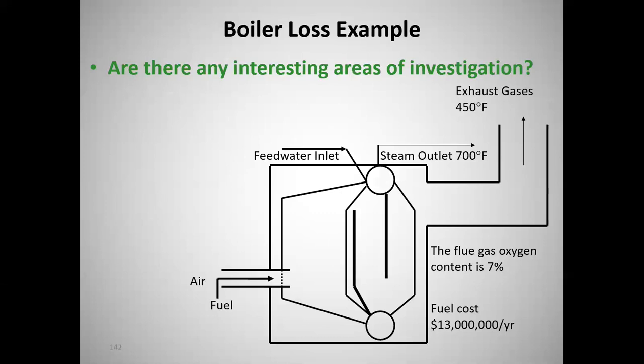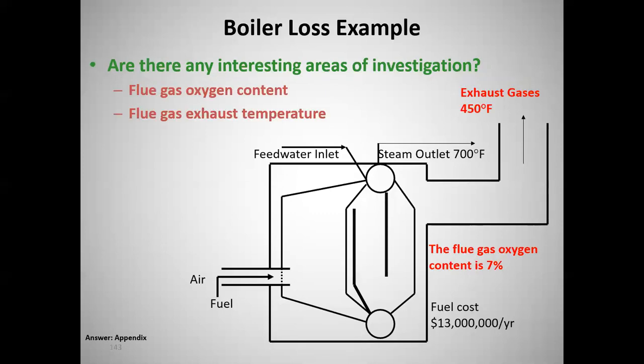Okay, so what would you want to look at? They hire you, a highly paid consultant. You come in, review all their data, sit down, talk to their boiler operators, get this picture on the board and say, well, boys, we've got to save some money here. I've got to justify my $10,000 fee for coming in here for a week. Well, the first thing I'd look at is I don't like 7% on a natural gas boiler. I think we can do better. I think we could at least tune this thing up. And I'm not real crazy about a 450 degree stack temperature.